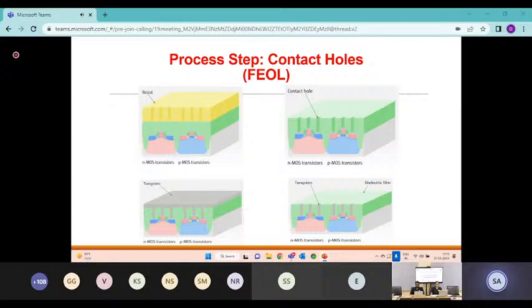Metal lines for conducting paths. So the holes are etched in this dielectric film, and these are then plugged with tungsten, and this dielectric film remains, over which the metal contacts are laid in the back end of the line. So this is the first contact with the source, drain and the gate. So this is the first material that is implanted.